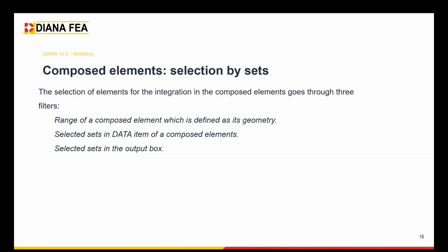It is important to note that none of these filters are mandatory. So if none of them are defined, the whole model will be used for the calculation of forces and moments. But if you choose more than one of these filters, the intersection of these filters will be used to define which elements will be assigned to the composed element.